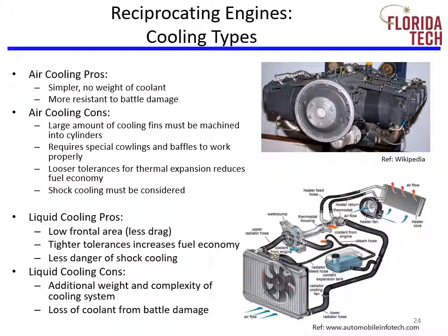There are two major ways to cool engines: air along with oil, and liquid cooling, which uses coolant much like a car. For air-cooled engines, oil passes through an oil cooler and proceeds to not only lubricate but also cool the engine. As the cool oil touches the hot engine, there's a heat exchange, meaning the oil becomes warmer but the engine becomes cooler. Then the oil returns back to the oil filter and oil cooler, and the process starts over.